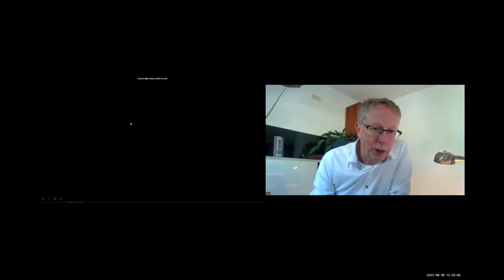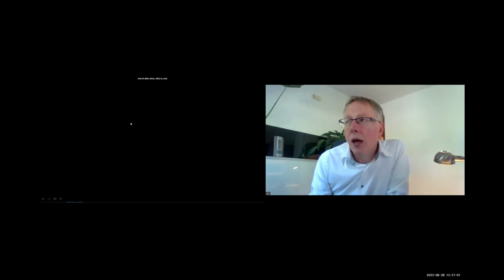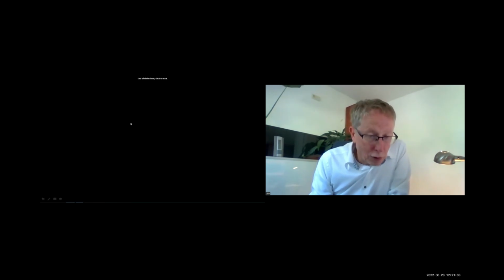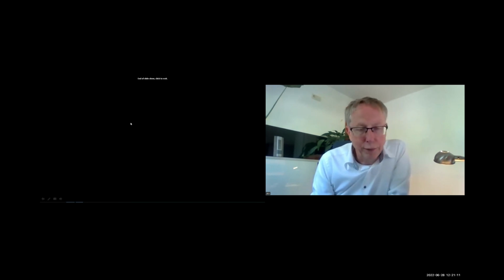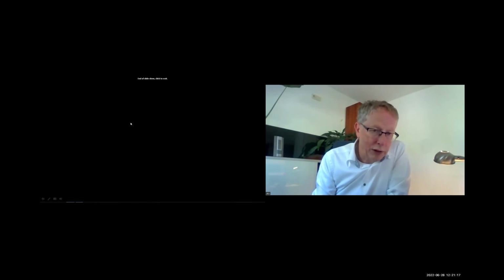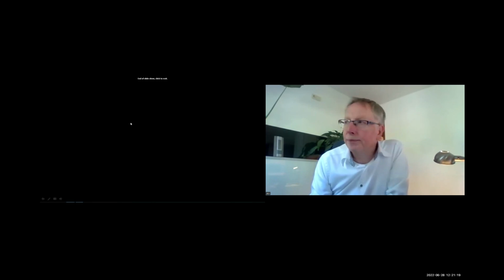In case of toluene, you will find a layer of toluene on top of your water. In case of, for instance, chlorinated hydrocarbons, which are mostly heavier than water, you will find a layer below the water phase. So that can be skimmed off, and therefore you get your solvent as a pure product out of the system.